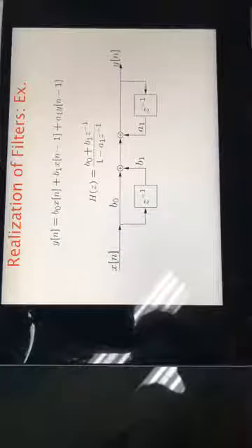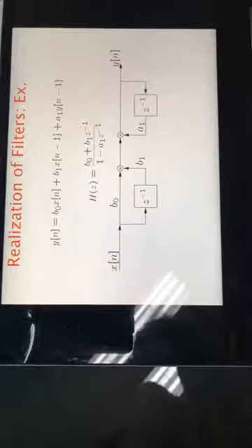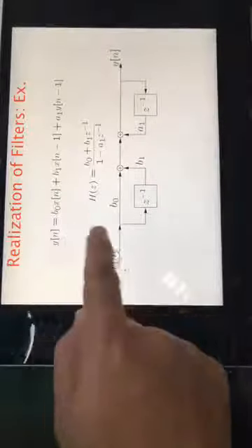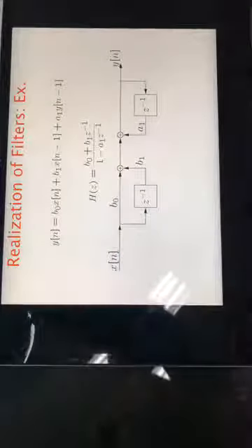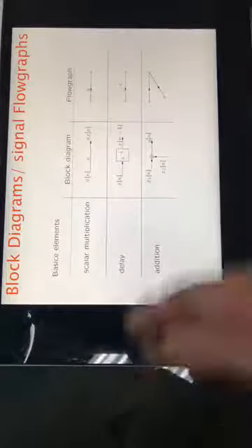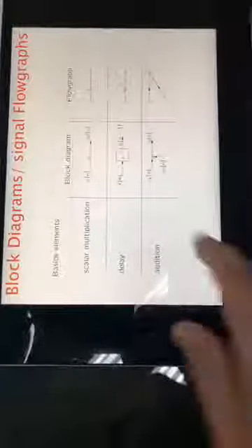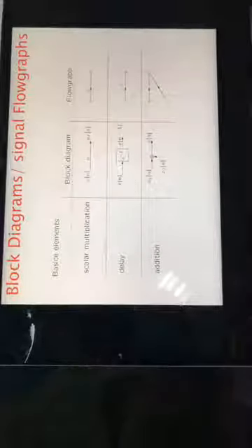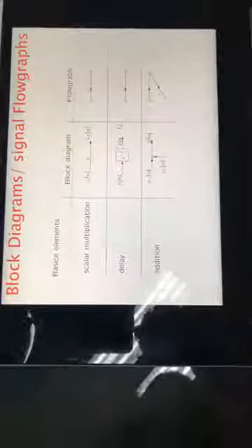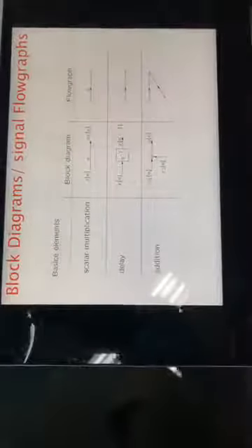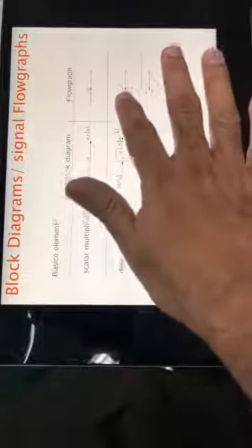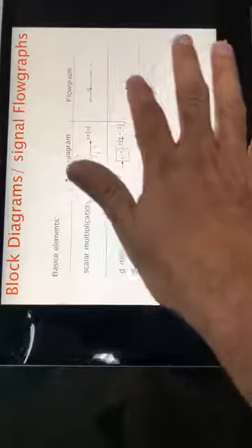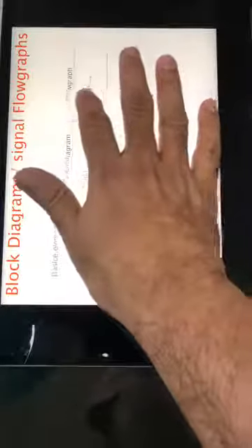Okay, this is the same example, just with a single coefficient, an equation which has only b0 and b1, and only a1. And then we have studied that instead of block diagrams you implement flow graphs. Flow graphs can also be drawn like this, where the two arrows meet, it means an adder. On an arrow you write z inverse, it means it's a register, a delay element, or a storage, or if there is a constant, it means it's a multiplier.